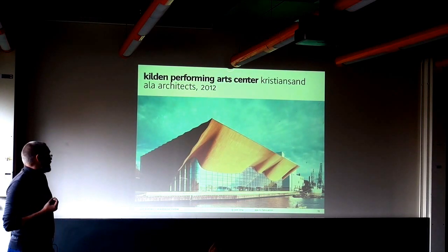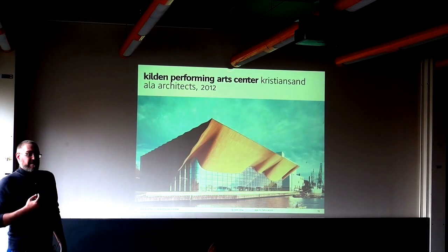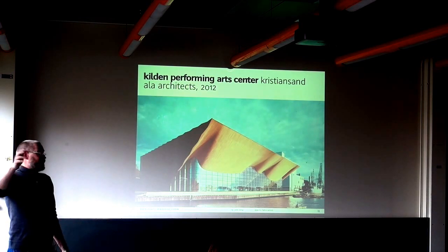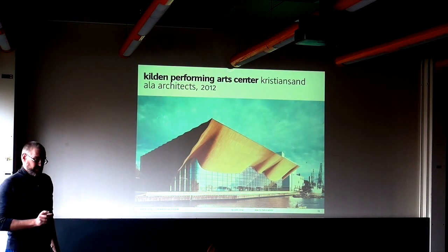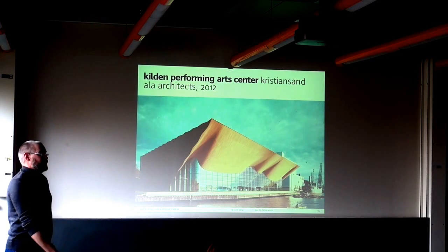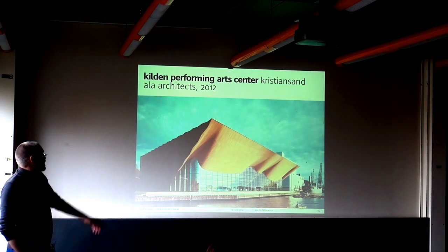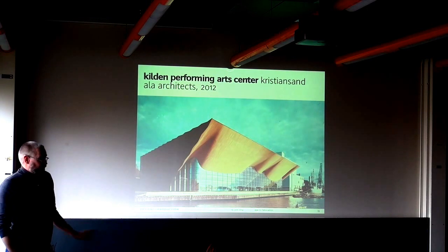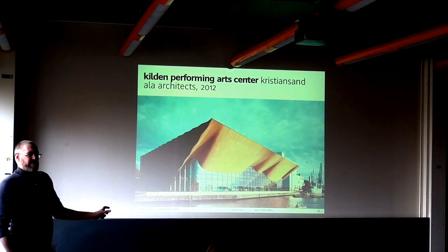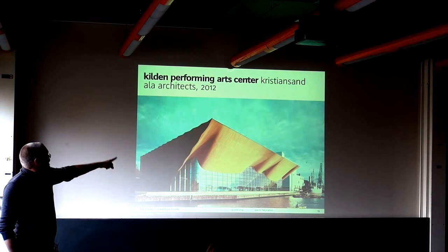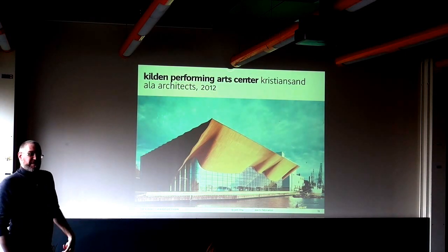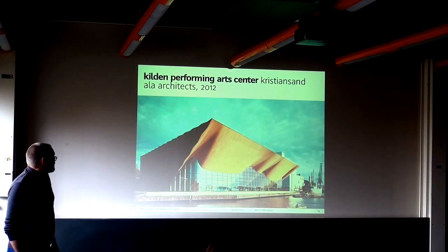There's about 3,500 square meters. The image, of course, is a curtain blowing away in the wind, and one of the design ideas was to have those oak boards running down the facade with 10 millimeter straight gaps in between them from the top down to the ground. The boards start at 120 millimeter width at the floor, and then get, of course, narrower and narrower to the top, because the straight line on the edge is shorter than the curved line on the floor.